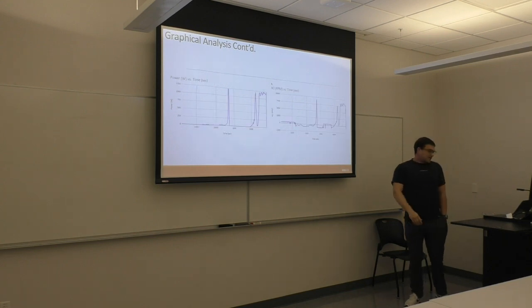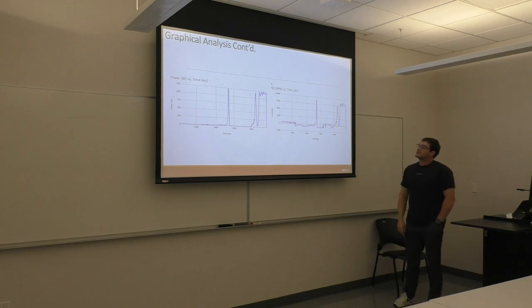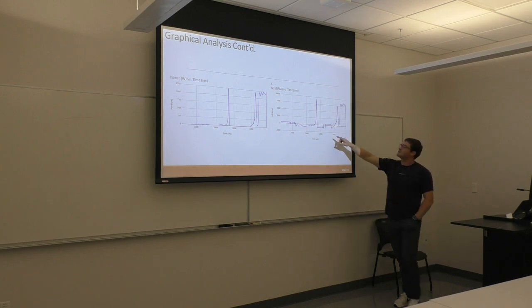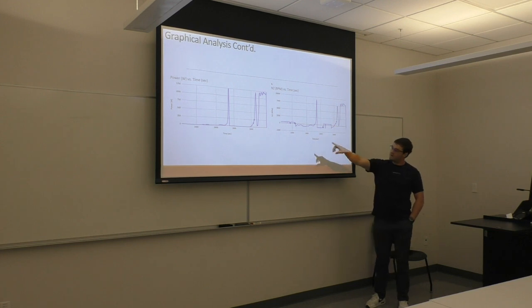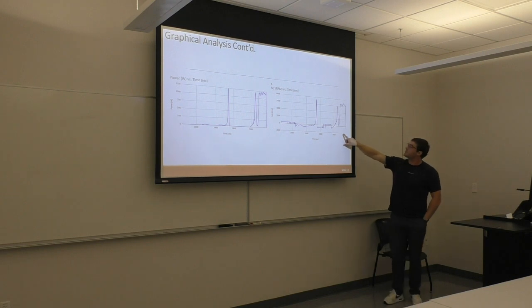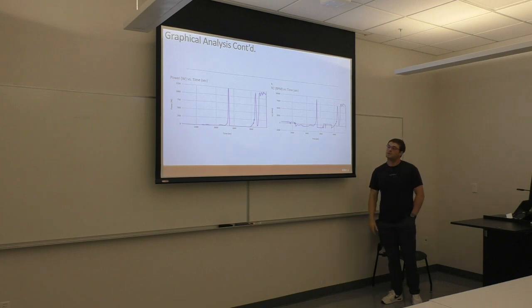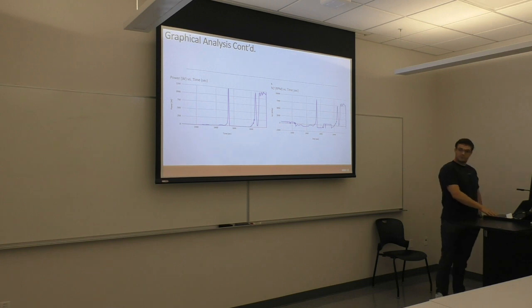And you have your power and your N2. N2 is our second turbine, which is spinning our alternator, which is going to give our power. We see a spike at around 2,700 seconds in our power, and after 3,000 seconds we can see that being reflected in our power as well. So as you increase your N2 RPM, your power is going to increase as well. It's pretty equal with it.